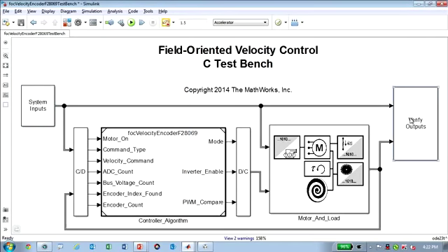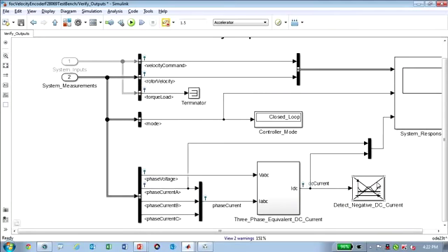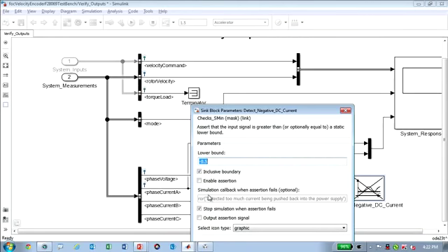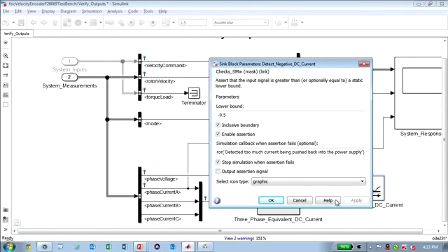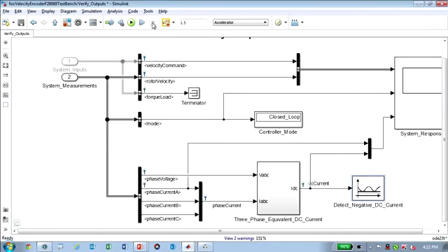So in this verify outputs, what we did is we basically added an assertion block. So if you're in the HMI session, you saw Jason do something similar when he's debugging for HMI. And I'm going to enable this assertion. What this is going to do is it's going to detect if I push a negative half an amp back into the system. So I'll run the system.